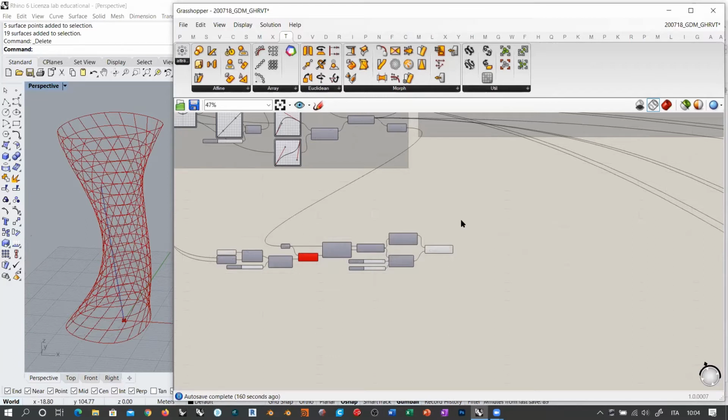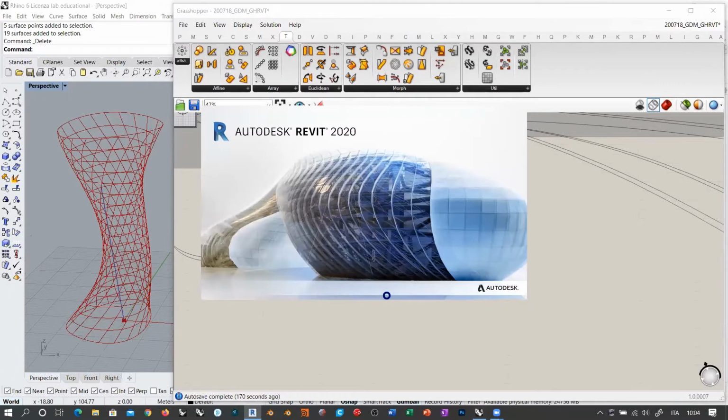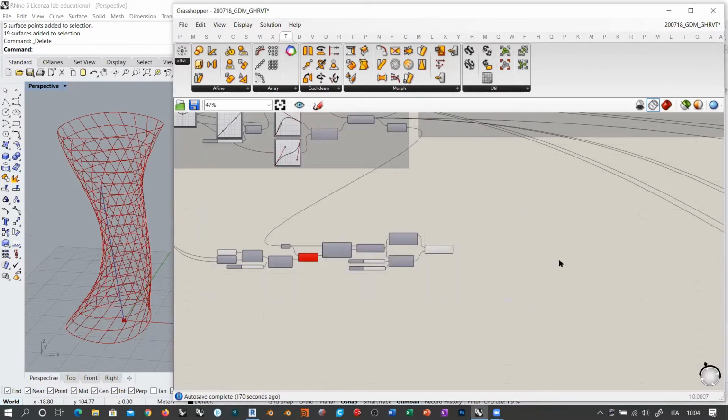There are some things that cannot be solved automatically in Revit. One of these things is the stairs. By the way, let me open Revit in the meanwhile. So you see that Revit is not capable of solving the node between the stair and the floor automatically, or totally automatically. Another thing that can happen, for example, is the node between walls and floors.